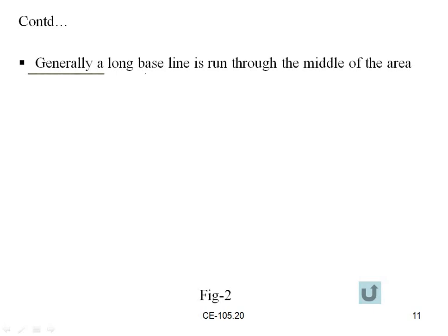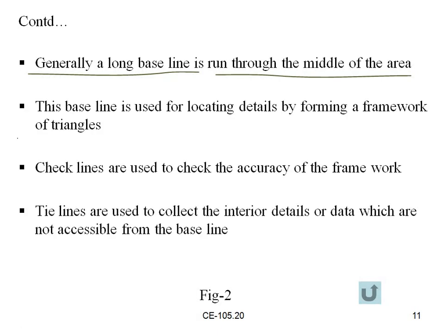Generally, a long baseline is run through the middle of the area. Let us see the figure 2 diagram. This baseline is used for locating details by forming a framework of triangles.